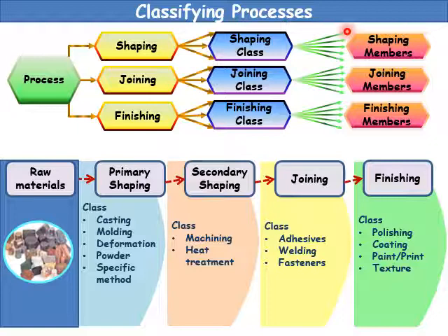After the components are made, the assembly of the components into one product needs to undergo a joining process. Joining processes include adhesive, welding, rivets, and fasteners. After the joining of all components, finishing processes are required according to the design requirement. For example, surface finishing of SA 2.5 is by using machine grinding and sandblasting according to ISO standards.